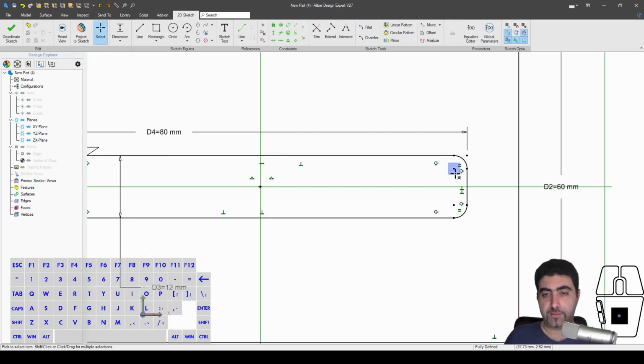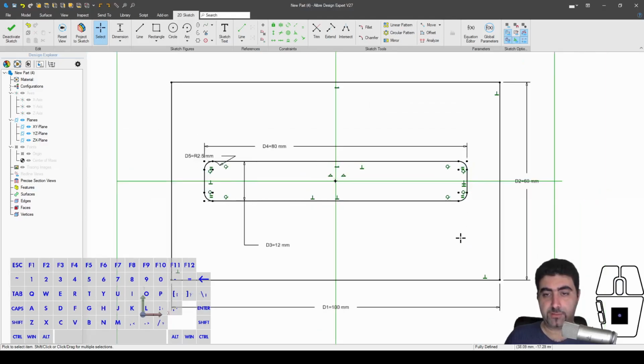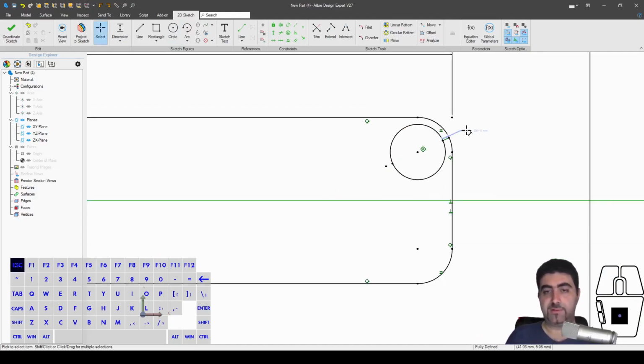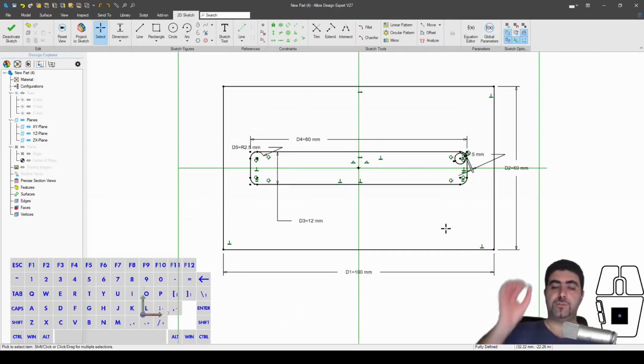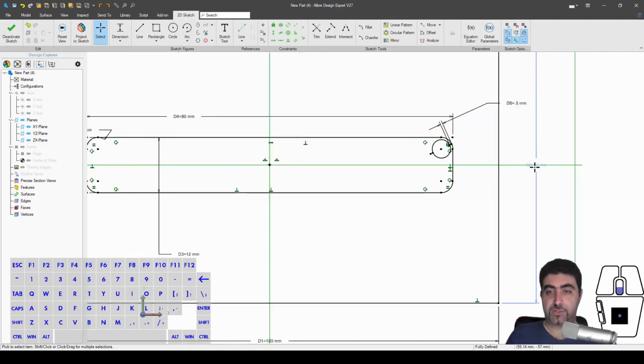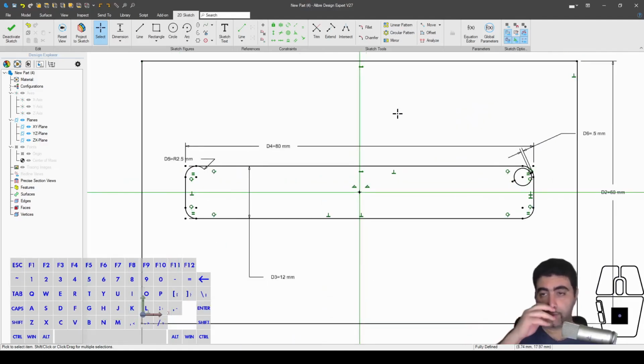And on the edge here, I'll have a little post that has a distance to that edge. So it's concentric with that fillet, and it has a distance of 0.5 millimeter. And that post is going to be a third level up, okay? So how do I use this layout sketch now, which I drew? How do I use it without redrawing it every time?